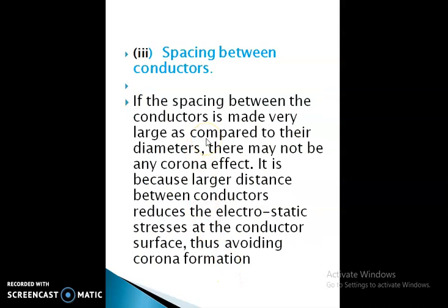Spacing between the conductors. If the spacing between the conductors is made very large as compared to their diameter, there may not be any corona effect. It is because a larger distance between the conductors reduces the electrostatic stresses at the conductor surface, thus avoiding corona formation.